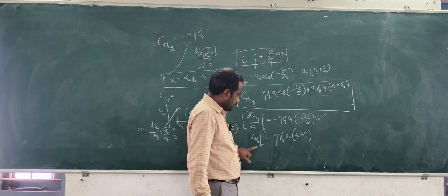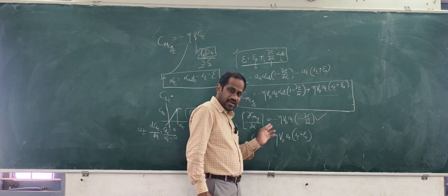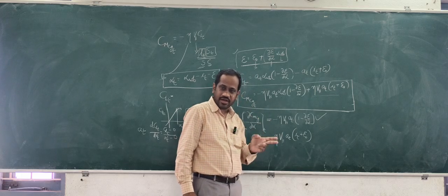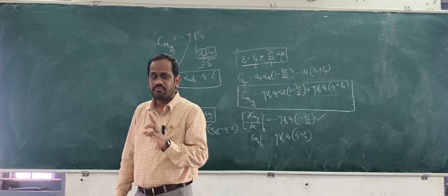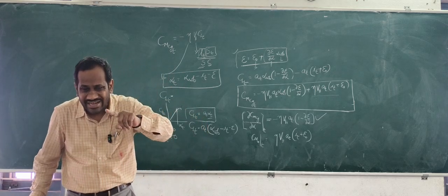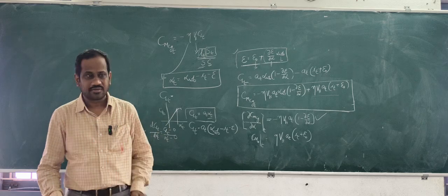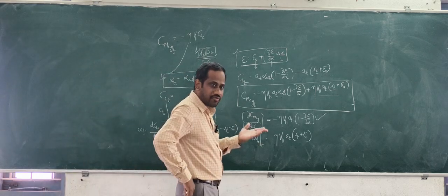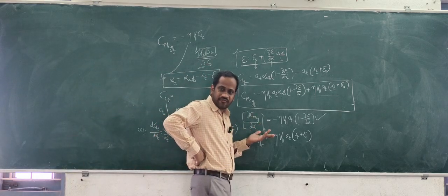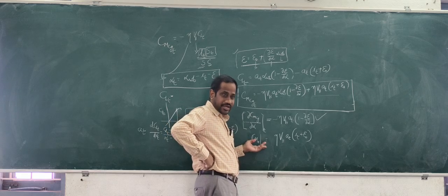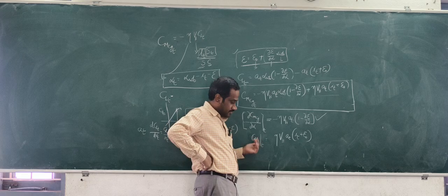Finally, for the whole aircraft, fuselage, wing and tail, CM naught should be positive. So contribution of the wing is negative. Look at the tail contribution to CM naught. How to balance the aircraft at positive angle of attack. So by attaching the tail, is it happening?